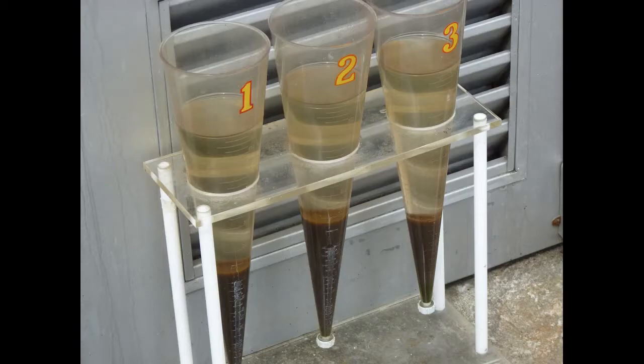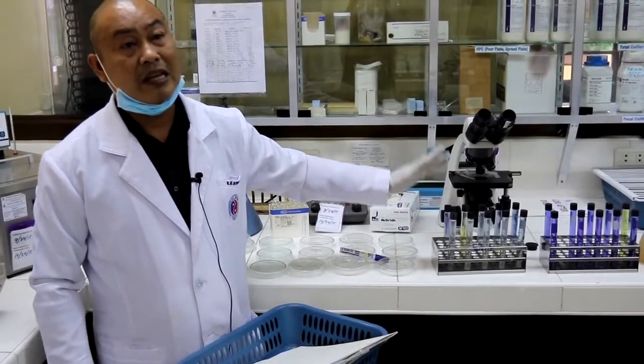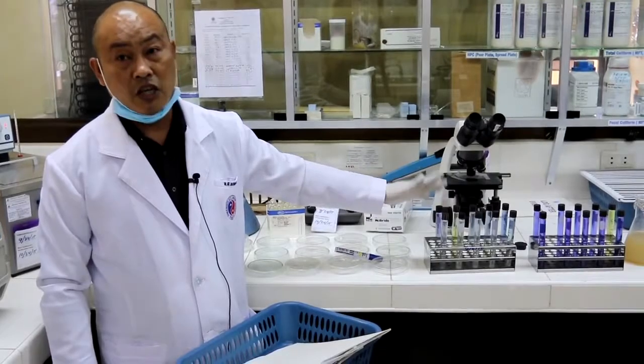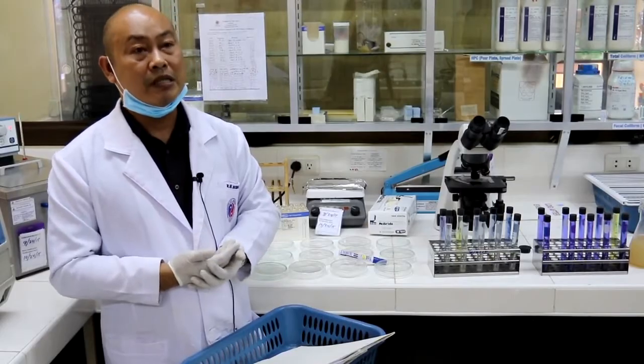The type and frequency of the tests required will be determined during the permitting process. It will be different for each plant. Important for most plants is an indication of the effluent quality in terms of microbiological activity. Fecal coliform, total coliform, and E. coli tests are quite common. At Dumaguete, they do the total coliform test. If there's a change in color, because there's an indicator included in the sample and the medium, it indicates bacterial presence.